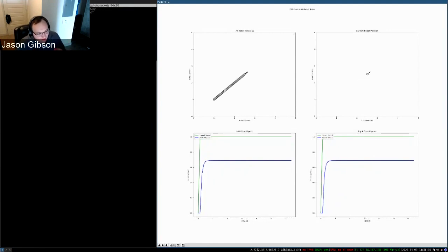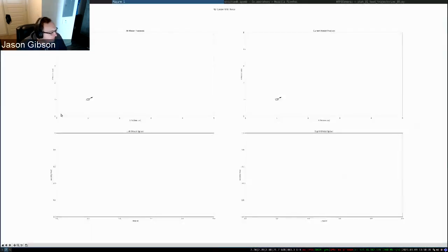How you tune P really depends on your application. At least for what I do, I do aggressive autonomous driving for my research, and what you tend to see is we want to over-tune it a little bit. That's probably what you're going to see me do here in a second. It obviously just depends on what you're trying to do. If you really want to reach that set point quickly, and it doesn't matter if you overshoot as much, then it's usually good to get your P a little high. So we increased our P, and I'm going to increase it again.